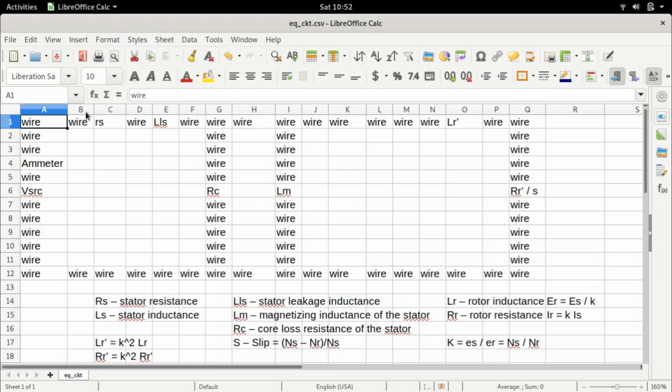As we already said, we can represent the single phase induction motor, and for that matter almost any machine, in a per phase equivalent circuit, which represents both the stator and the rotor. And of course, since it's a machine, there is a speed dependent term, which is the slip. The slip is defined as the difference between the synchronous speed and the actual rotor speed.